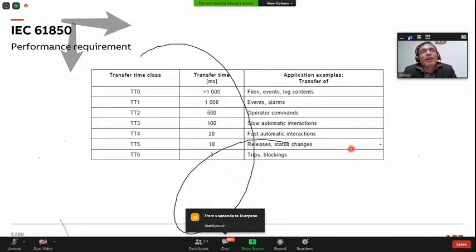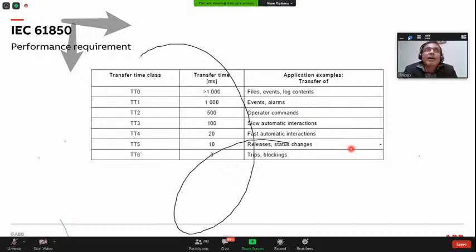The device continuously looks at the packets in the network, and it knows that this Goose has come at 4 millisecond, and I am expecting the same packet at 8 millisecond because of the retransmission I explained, and then maybe 16 millisecond. If the stack sees that there is missing data, it can say there is a communication failure somewhere, that I am not getting the data which I am supposed to get.